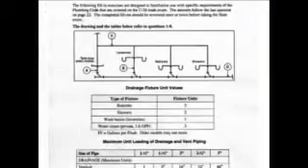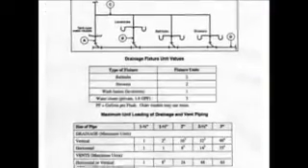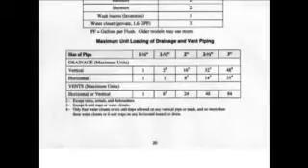The minimum size pipe permitted at A is, now we go back over to the other page and we look on the bottom chart. We're going to be looking at vertical drainage. We have 6 units that need to be covered, so we'd be looking at least at 16, which is under 2-inch size pipe.